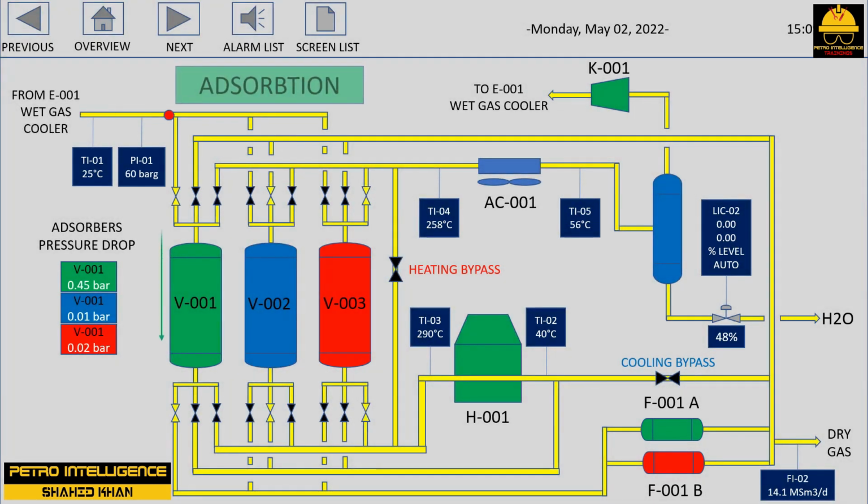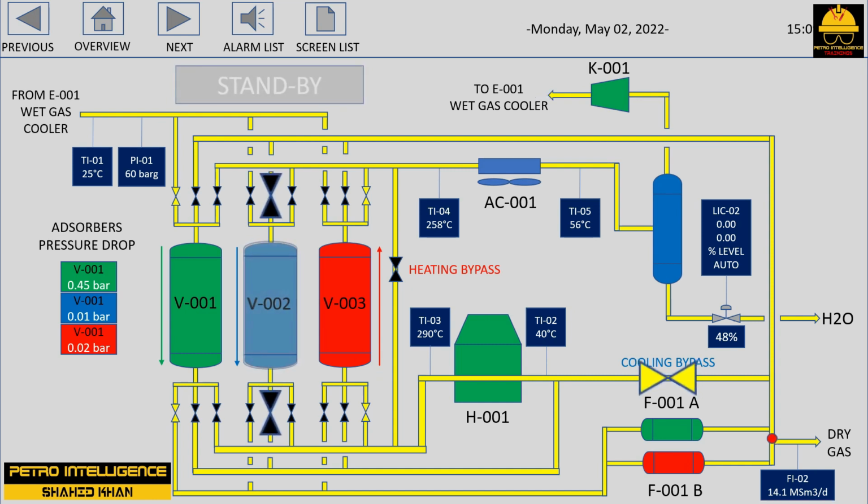Regeneration usually takes place in 4 steps. 1. First, after the bed is bypassed, the process stream is displaced from the bed by draining it or displacing it with another chemical. 2. The bed is sometimes washed or flushed to remove any remaining process chemicals as well as solids, dirt, or trash. 3. The regenerating step itself involves soaking the ion exchange resins or purging the molecular sieves. 4. Finally, after regeneration, the bed must be returned to service. This step involves clearing the bed of the regenerative chemicals and preparing it for normal operations.